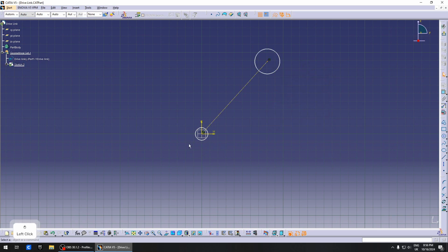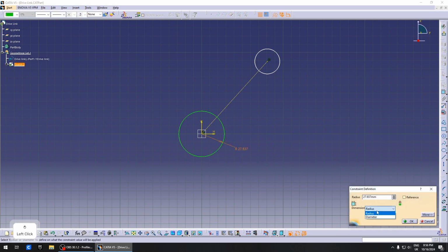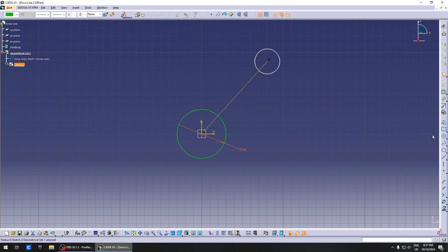In this case, it doesn't make that much of a difference, but if you ever update your sketch and decide to have this point not in the origin, then you're gonna have a problem, because it won't update automatically. So here we put the diameter, let's say 60 sounds about right. 60 the same.